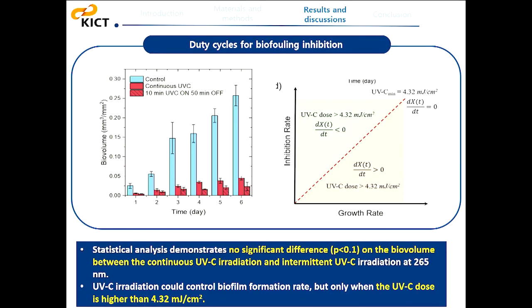Moreover, ongoing research suggests continuous irradiation may not be required to control biofilm growth. If the UV dose is greater than the bacterial growth rate, then biofilm growth is inhibited. Therefore, we are exploring duty cycling, wherein LEDs are cycled on for a short period of time and then off. This lengthens the operation time to several years before the accumulated dose approaches levels previously found to cause membrane defects to the polymer surface.